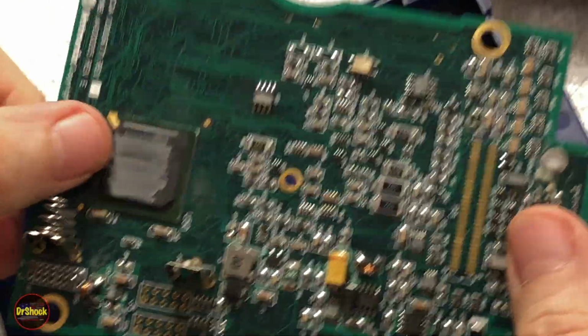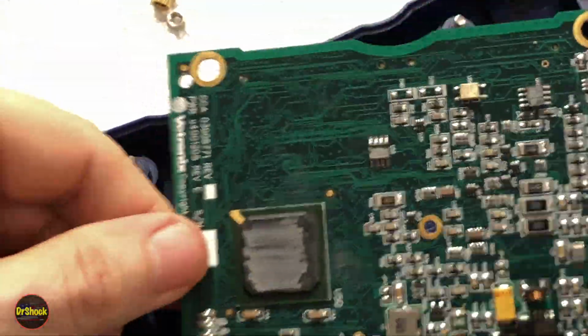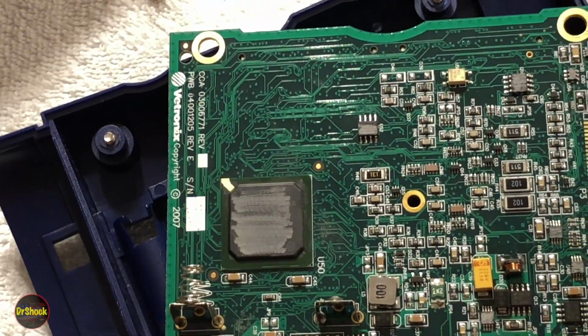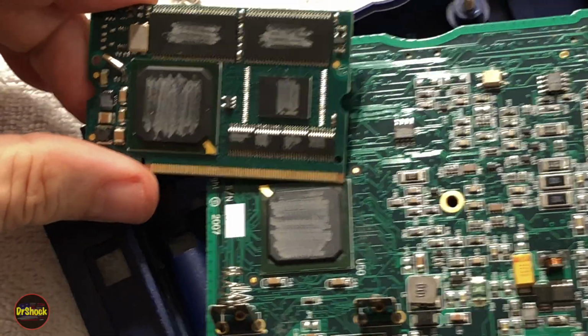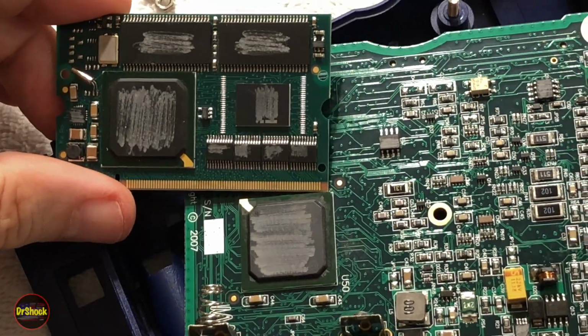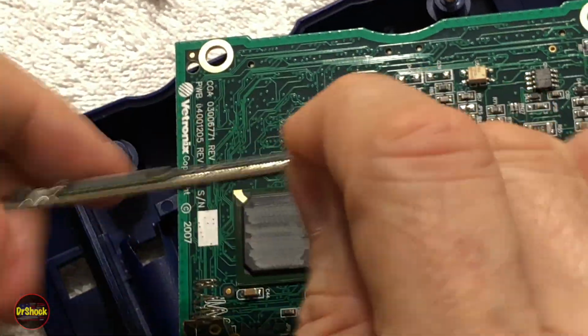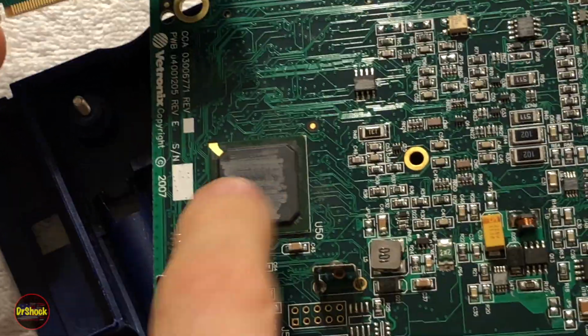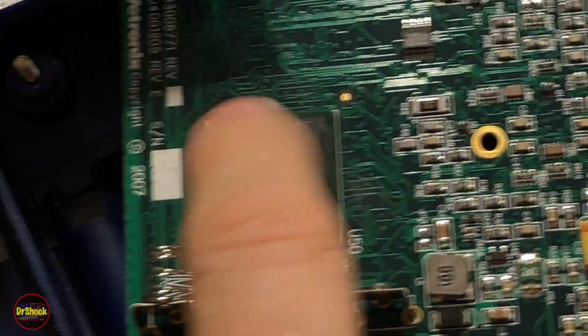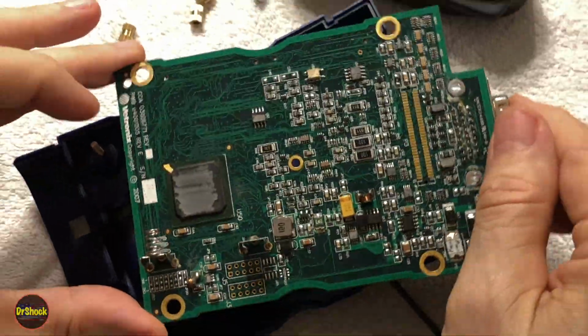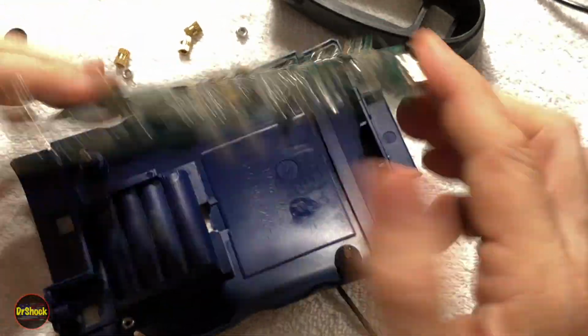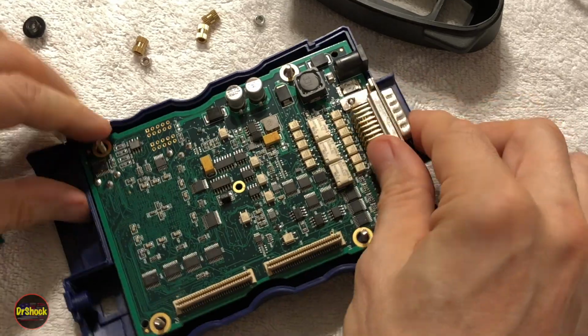And there's the FPGA. Now on these clones, for some reason, this is a very early style clone, so I guess they were afraid of other cloners copying their clone, and so they've etched off all the markings on the chips. But this is typically an Altera Cyclone FPGA. And so this whole board here is at fault for the problem that we're getting. So that's this one's diagnosis, this board here.